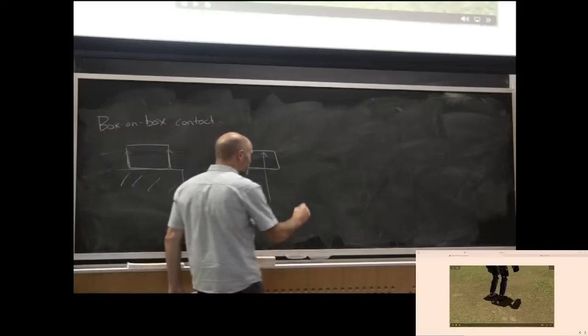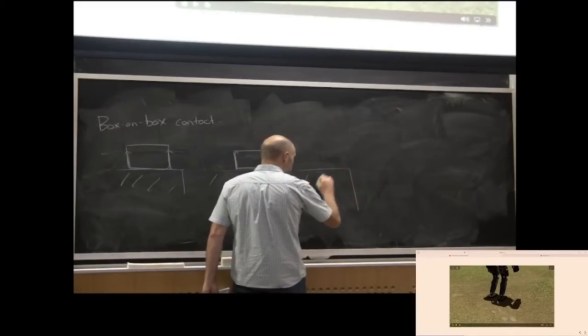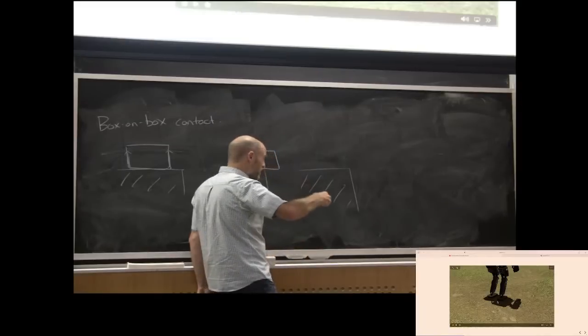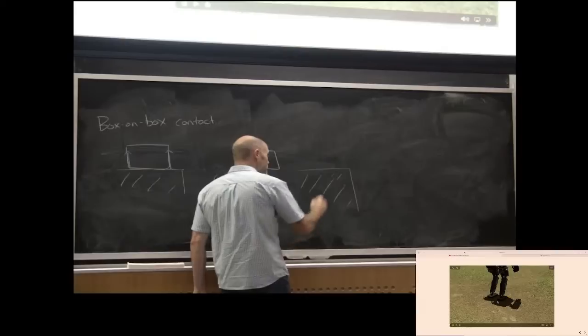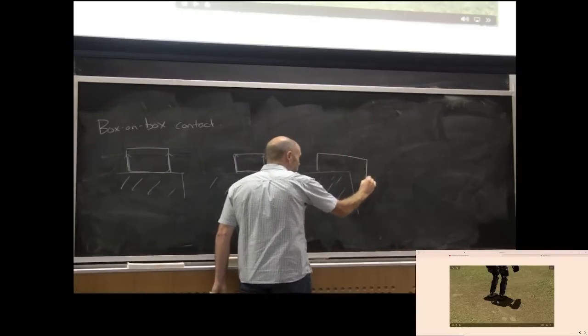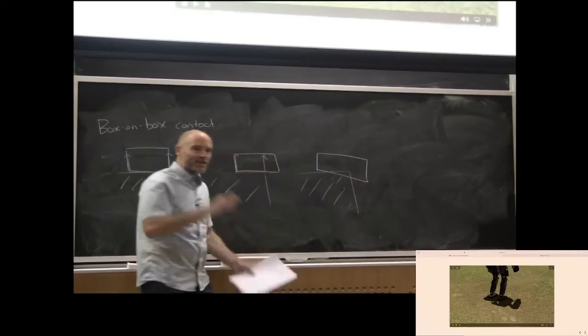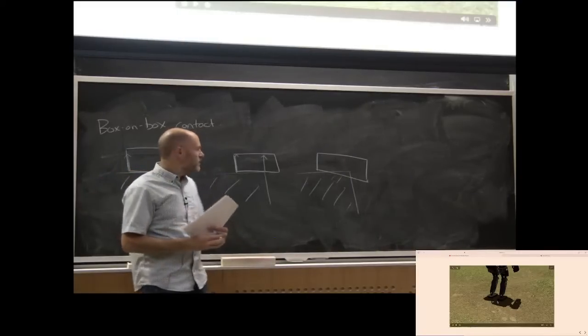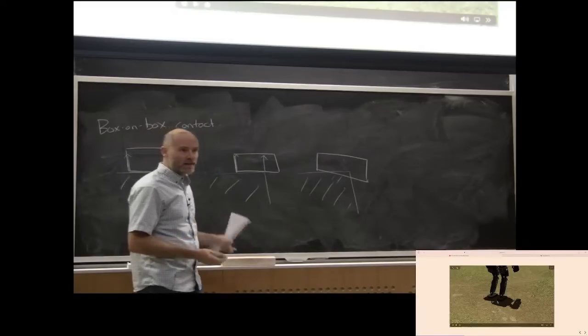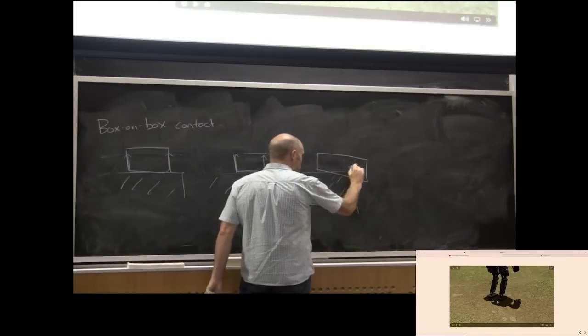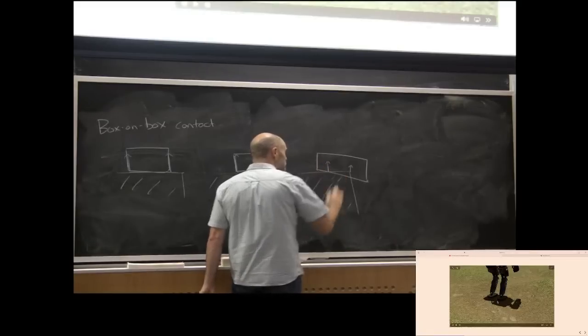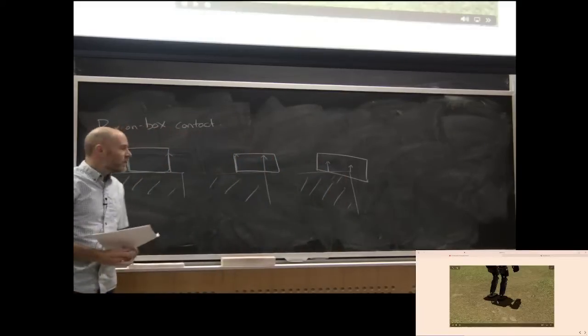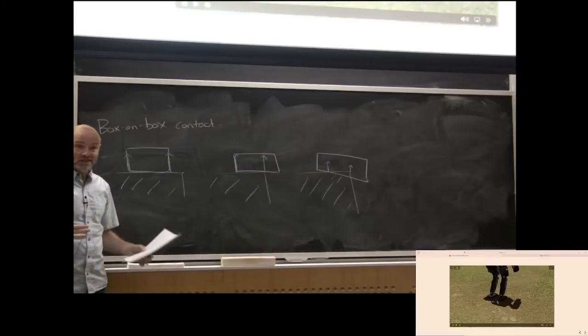But there's other cases too. Because the integration time step isn't perfect, and I might not simulate the equations perfectly, I might find myself with my block like this. My integration wasn't perfect, so my geometries are overlapping a little bit. Now where do you draw the contact forces, right? It's not super clear, right? Maybe you pick here, maybe you pick here. Writing an algorithm that picks those forces consistently is hard, maybe impossible, I don't know. I think it has never been done.